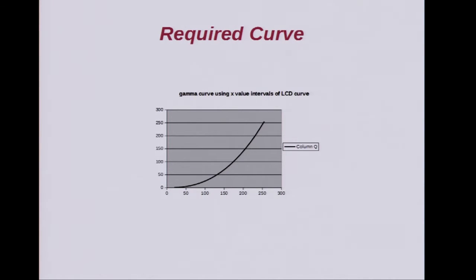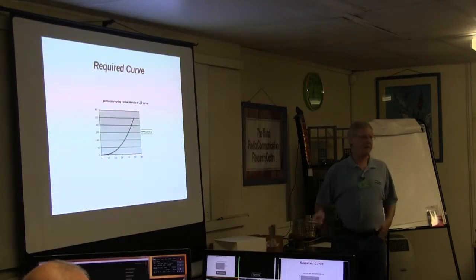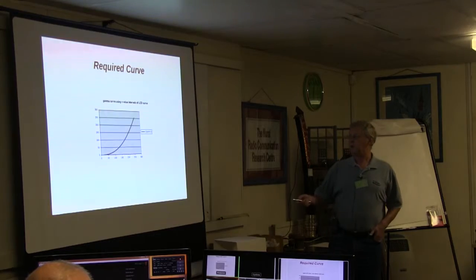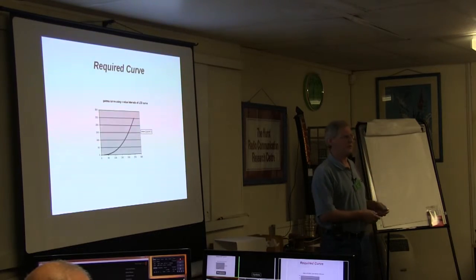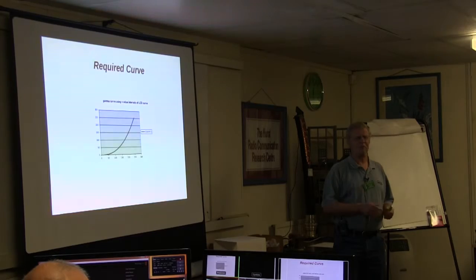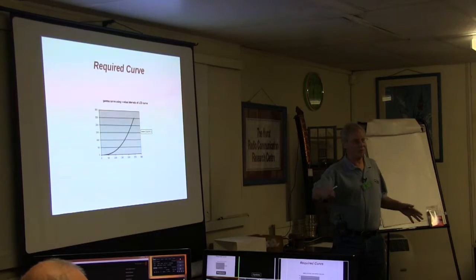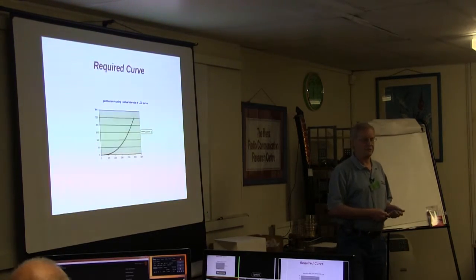So, the required curve, just going back and looking again, 0 through 255 if it was an 8-bit system, and this is probably, they use the term nits a lot in LCDs. 250 was a typical value. I think it translates to candelas per square meter. So 250 is fairly good. 300, 400 makes a nice bright display nowadays, and that's pretty easy to achieve.